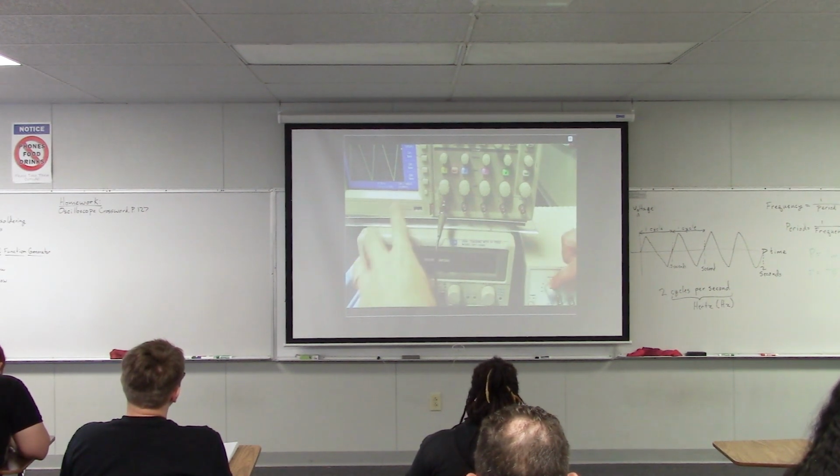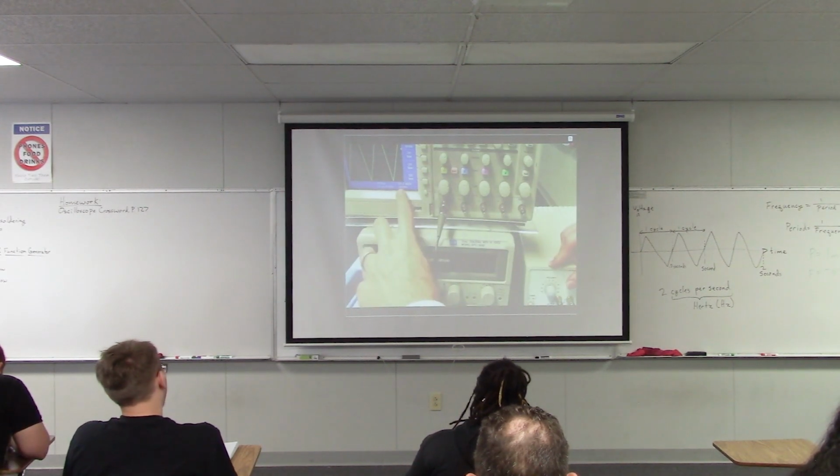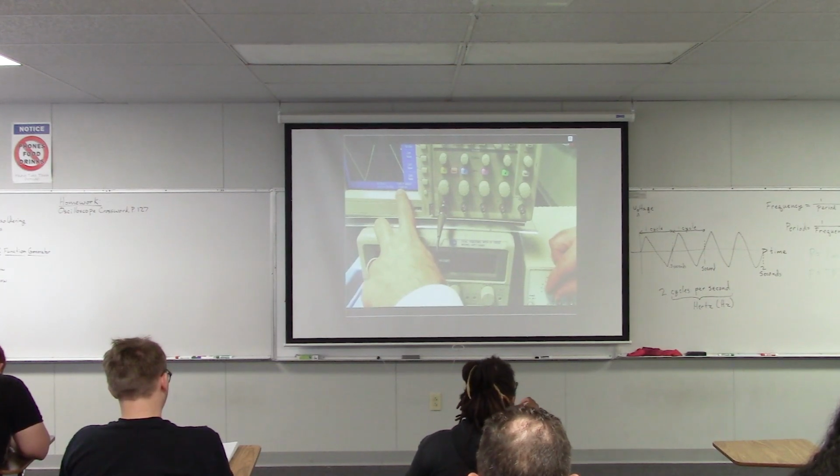So say I wanted a frequency of 500 hertz. What I could do is I could look at this frequency up here, this frequency measurement, while I turn this dial. So I could turn this down, and now I'm at 670, 589, and I could keep going until I get the actual frequency that I want. Oh, I overshot a little bit. I'll come back. So that way you can get a much more precise measurement than you could just by looking at the dial. So that's really what you would want to do if you were looking for a precise frequency. Does that make sense?